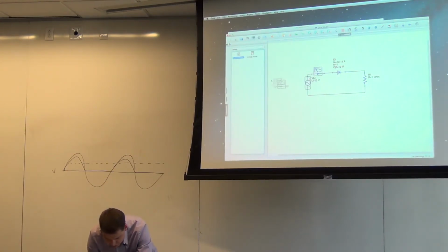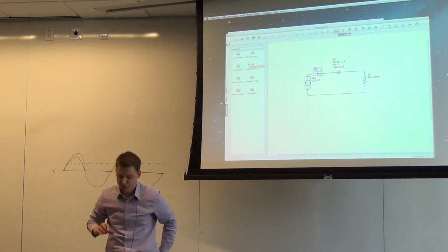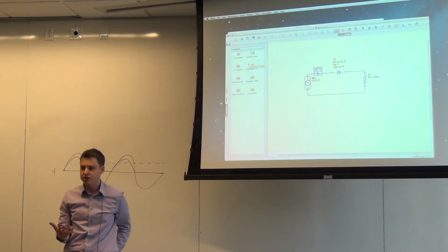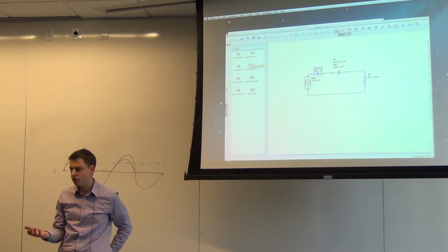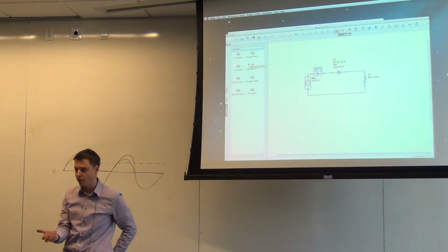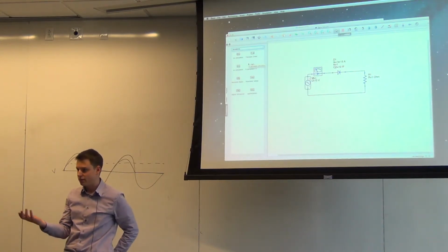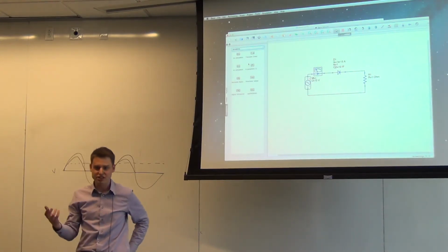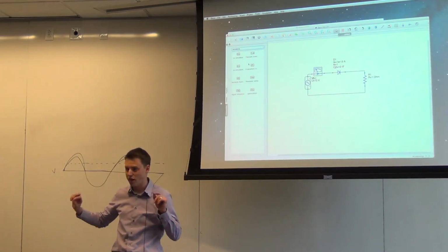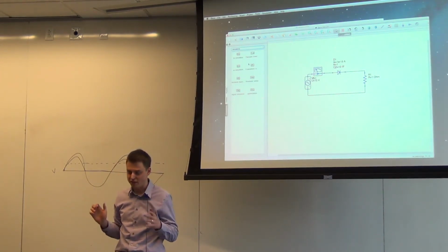Okay, so here's our simple circuit. We're doing something a little different this time, where instead of an AC or DC simulation, which simulates steady state AC or DC current and voltage, that's not what we want here. There is no steady state really anymore. You have to look at the actual evolution of the waveforms over time, or they don't make any sense.